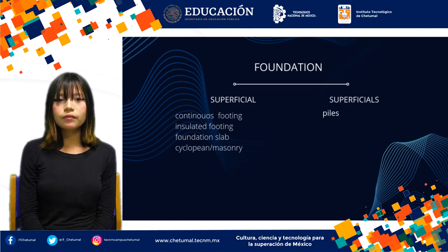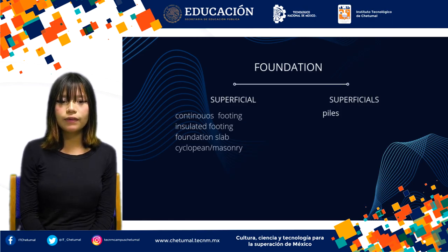Construction process. First, a layer of lean concrete or a base layer is placed, followed by a steel mesh across the entire surface. Then a thick layer of concrete is poured, creating a rigid and strong slab. Advantages. It distributes loads evenly, making it suitable for challenging terrains or buildings with high structural demands. However, it is more expensive and requires a larger quantity of materials.